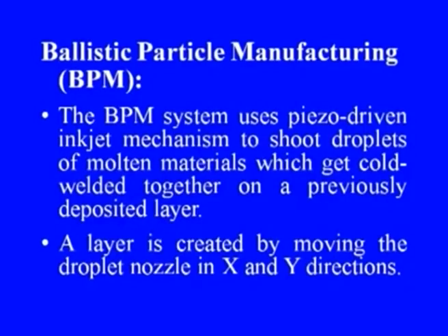Now, let us move on to another process, that is the ballistic particle manufacturing process, in short known as the BPM process. The ballistic particle manufacturing system uses a piezo driven inkjet mechanism to shoot droplets of molten materials which get cold welded together on a previously deposited layer.